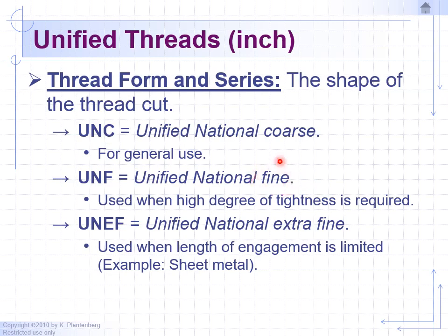Also inside of a combustible engine, where you have rapid movement inside, the parts inside with threads will have fine threads, tighter together. Now things like water pumps, where you attach it to the engine block or where you attach the alternator to a bracket, those will have coarse threads where there's no rapid movement, like high RPM, like on the wheel studs. Then you'll just use a coarse thread.